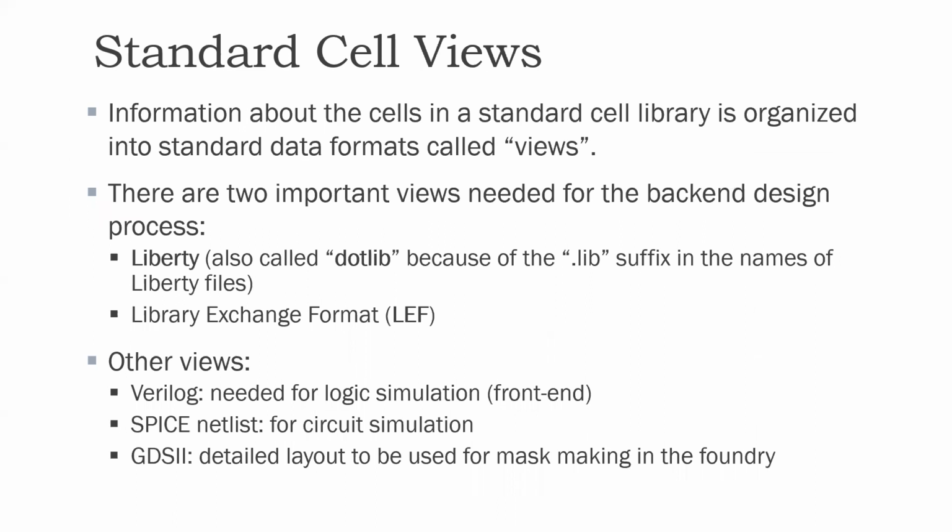Now, to use standard cell libraries, you need to have data of the standard cell libraries. The information of every cell in the library needs to be provided in order to be able to use the cell in implementing a logic circuit. And this information for every standard cell is organized into various files. These various files, we often refer to them as views. So the information about the cells in a standard cell library is organized into standard data formats of files, and these are often called views.